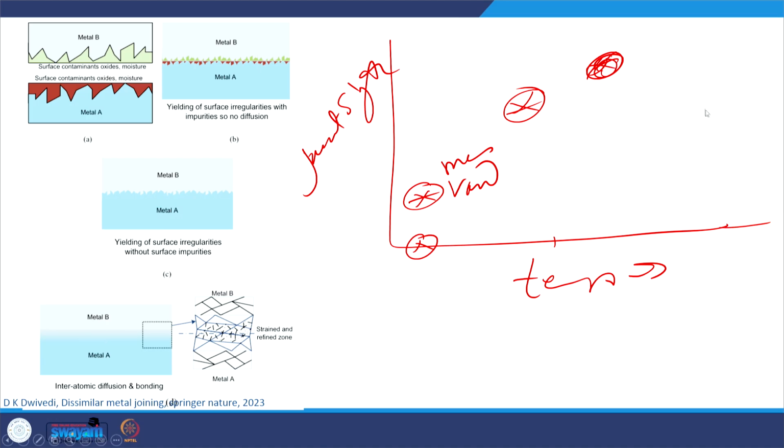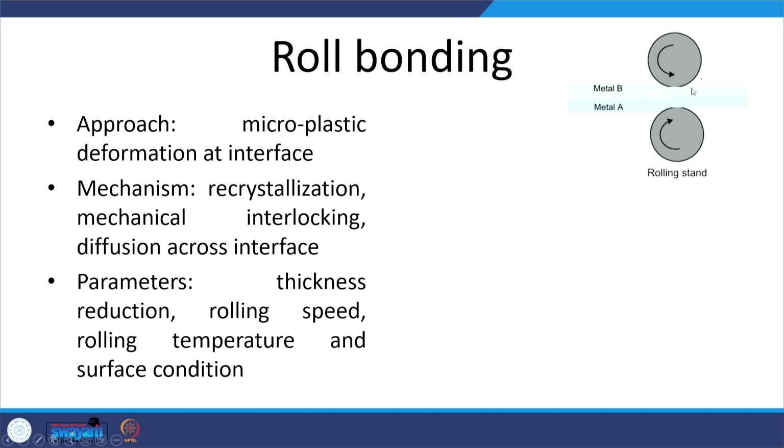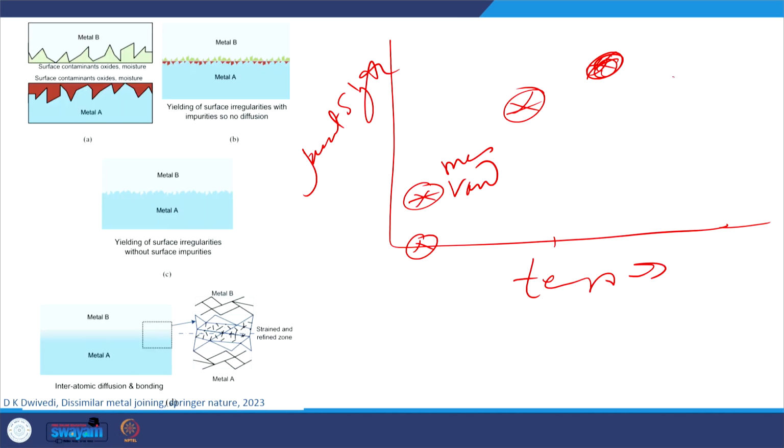But what can a further higher temperature cause? It can start the thermal degradation of the material itself. Because of overheating, the substrate material may start getting degraded. So, initially there will be an increase in joint strength, but when we go for overheating beyond the optimum value, thermal degradation of the parent material itself starts. So, here the joint may be good, but the base material or the parent material itself starts degrading due to the overheating.